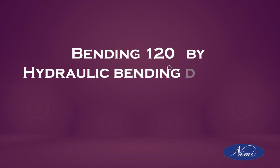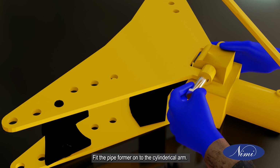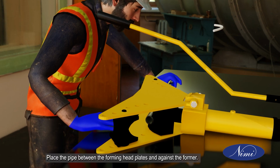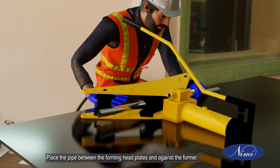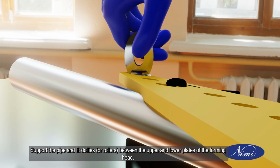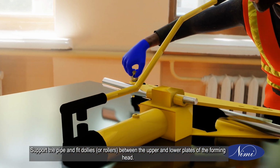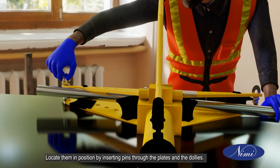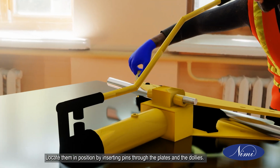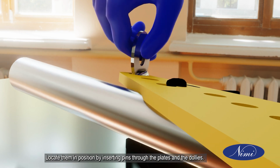Bending 120 degrees by hydraulic bending machine. Fit the pipe former onto the cylindrical arm. Place the pipe between the forming head plates and against the former. Support the pipe and fit dollies or rollers between the upper and lower plates of the forming head. Locate them in position by inserting pins through the plates and the dollies.